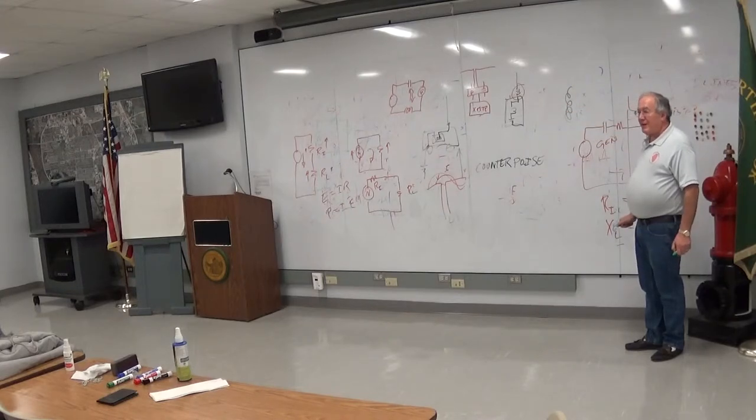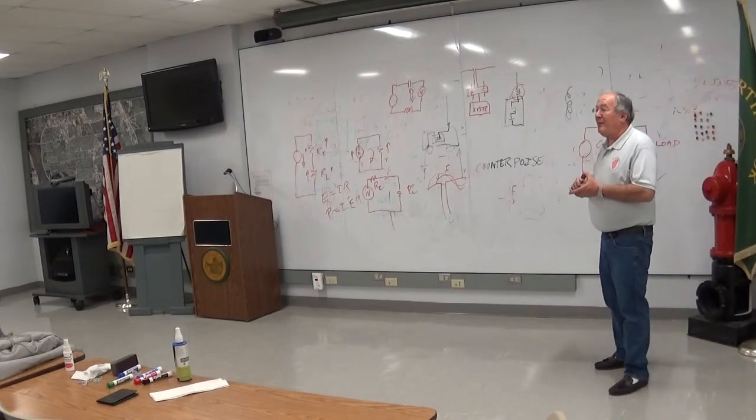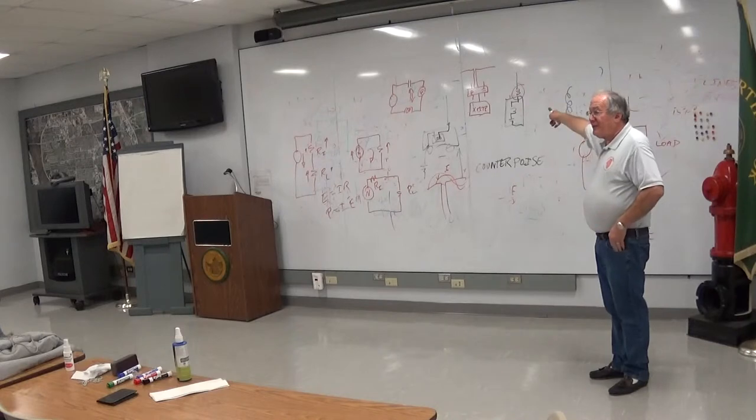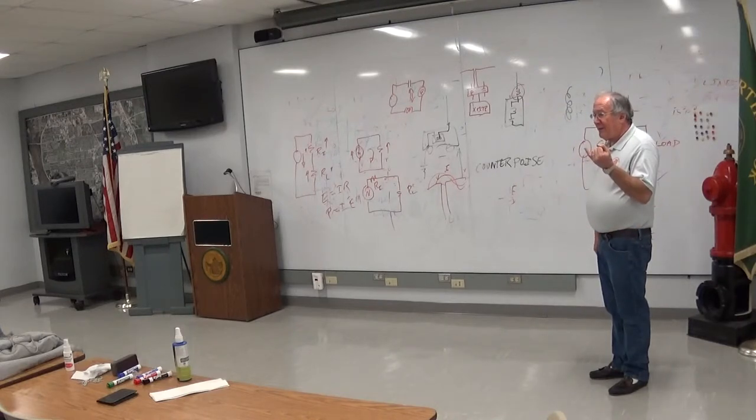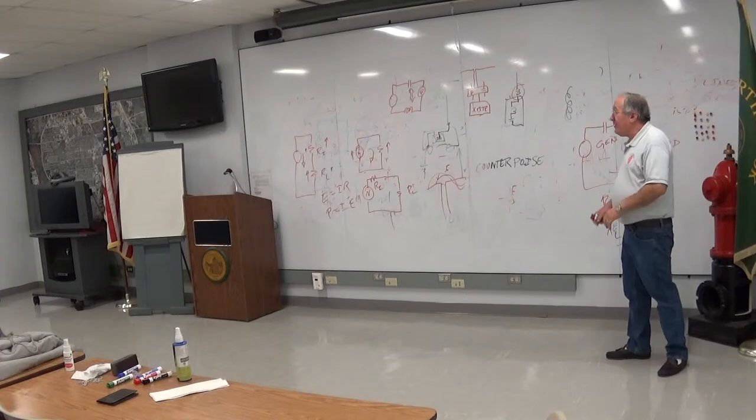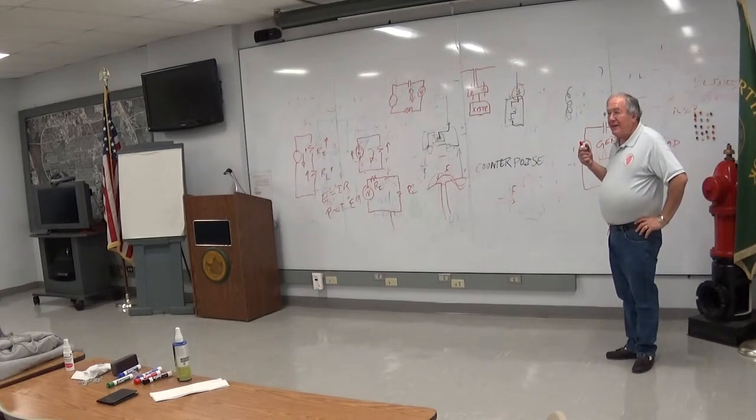reactance to what the transmitter has, or actually the other way around, the transmitter will compensate for the antenna's imbalance relative to the transmitter by adding inductance in the form of a capacitor or inductor, depending whether it's too long or too short, and resistance. And that, by the way, is how a lot of antennas operate these days. They're not cut for a particular frequency.